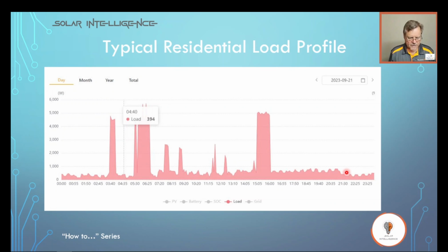So we can see the base load is in the order of between 500 and 800 watts. That's typical. It's a little bit high, but that's typical. My house is a lot more than that, and I can't explain why. Well, I can explain why, but I don't want to go there now. So typically, if you optimize your house, you can get the base load as low as 200 watts, 300 watts. That's a good idea, to minimize that energy.